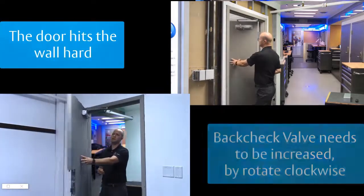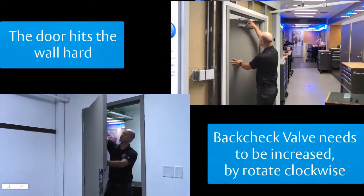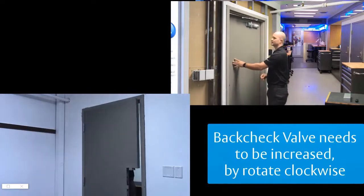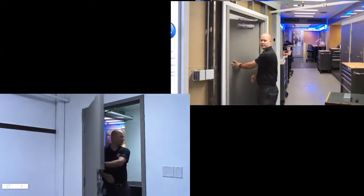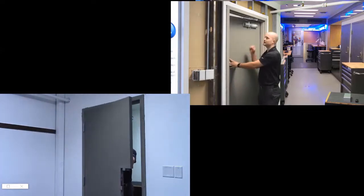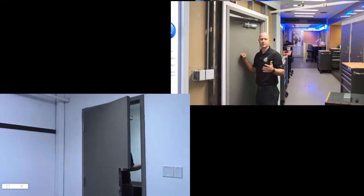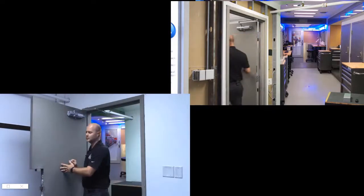Right there, the back check was a little too loose. So we'll give our back check half a turn and try that again. Right there, that's about what we want for our back check. The door did not stop abruptly, but came to a stop with kind of a cushion. That's what we want. Next, I'll open the door to the 90-degree point